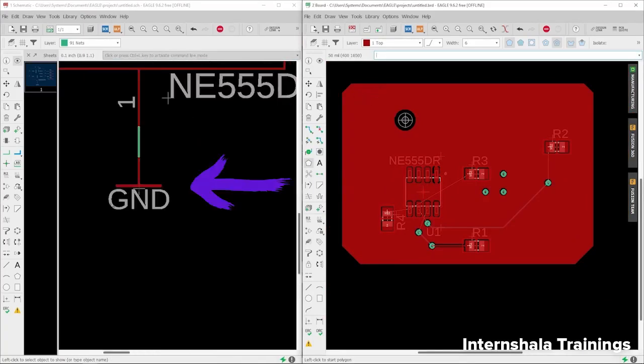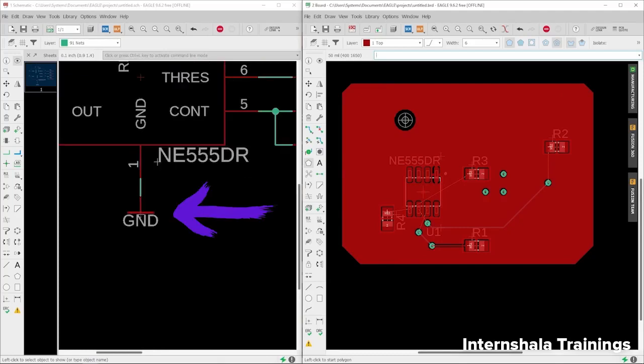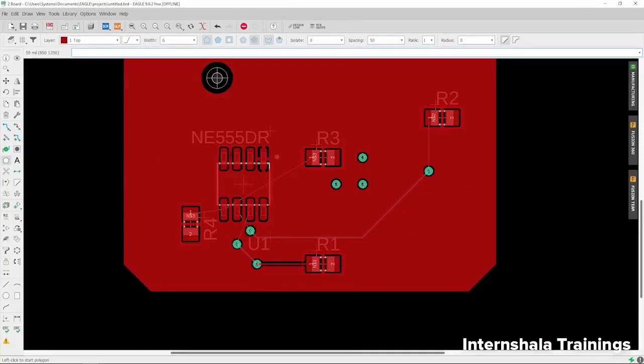The reason was, you can see here, the symbol name is GND. Instead of this ground, if we had a power symbol of plus 5 volt here, then in that case we would have provided the signal name as plus 5 volt. Okay, so I hope that this particular point related to polygon is clear now. And if you still have any doubt, then you don't need to bother about it, because when we create the layout for our hardware, at that time this point will be clear to you.